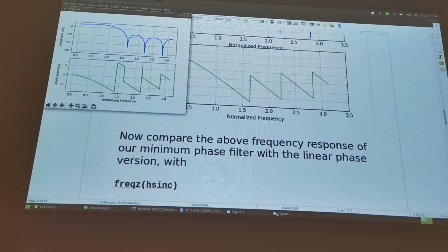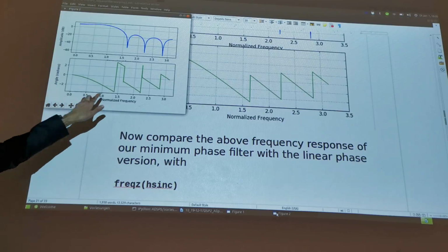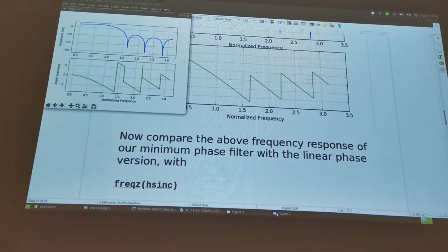Right, but what's the difference between 0 and pi? Well, basically it's switching the sign, right? So you go from +1 to -1. And this again is basically a factor, and factors don't really matter for filtering, because you can always compensate factors by just multiplying or dividing by them. So this is again an artifact from this design. This design gives us an opposite sign, and that's why we get this wraparound at this position and not here. And that's also why it looks so different.